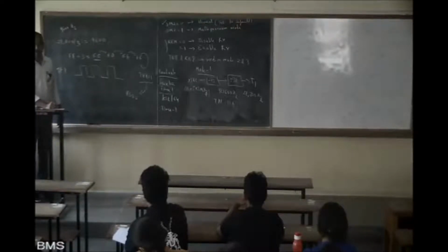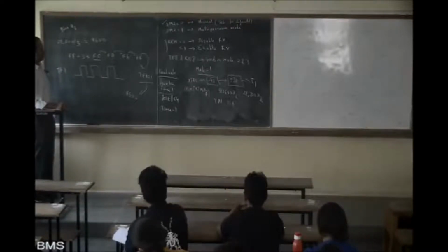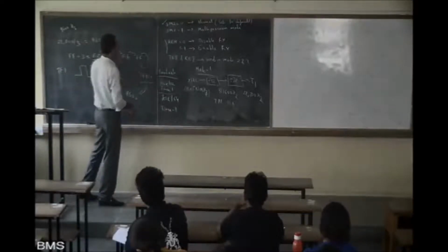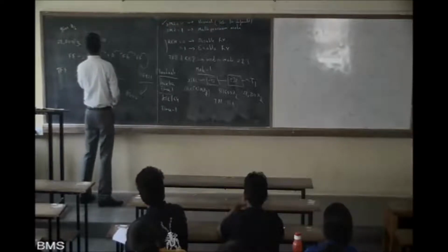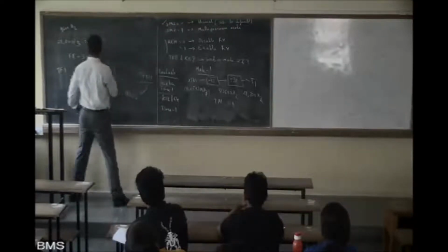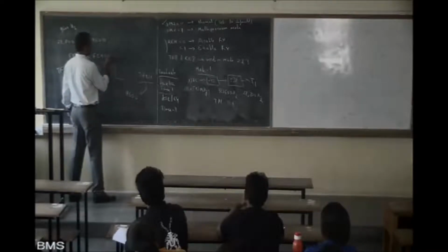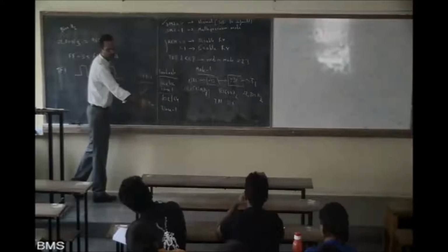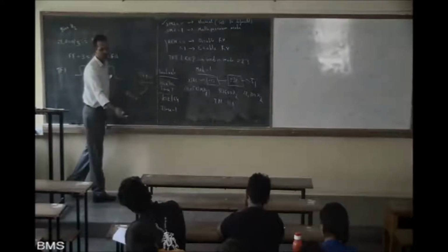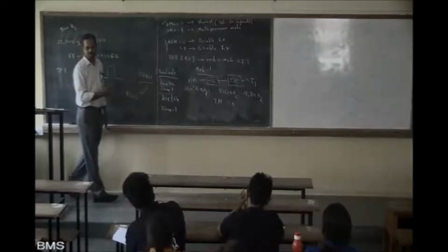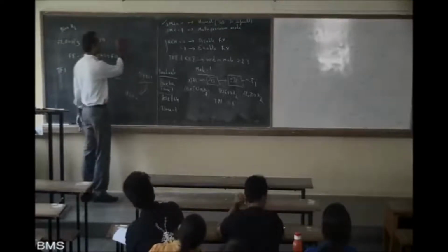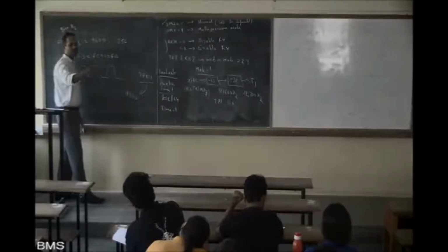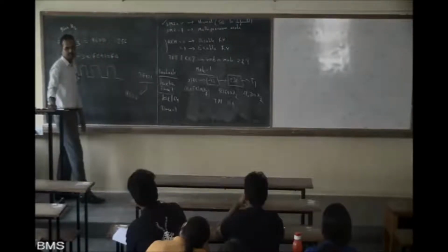You are getting what I am saying? Hey, one second here. The counter has to overflow, right? It is FC, correct, plus 1 is FD. When it goes from FF to 00, then the TF flag will set. So plus 1 has to be added. In that case, we have taken 256, but actually FF is 255. If you check our previous calculation.